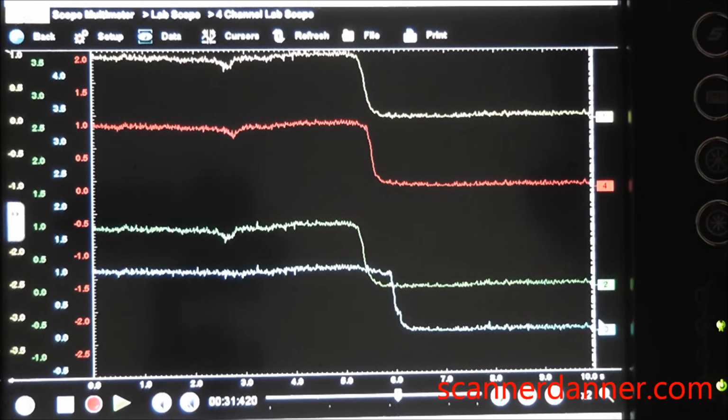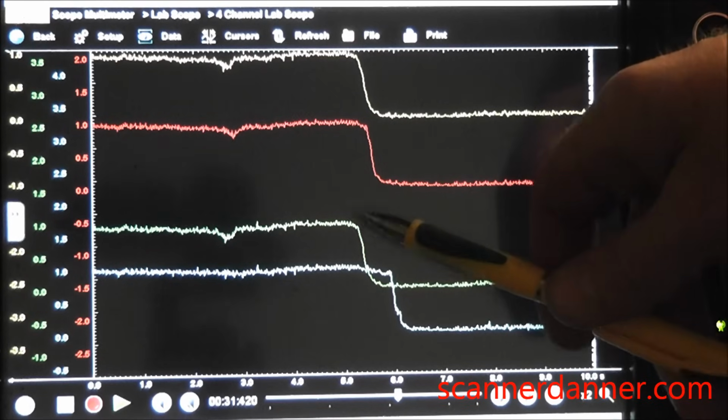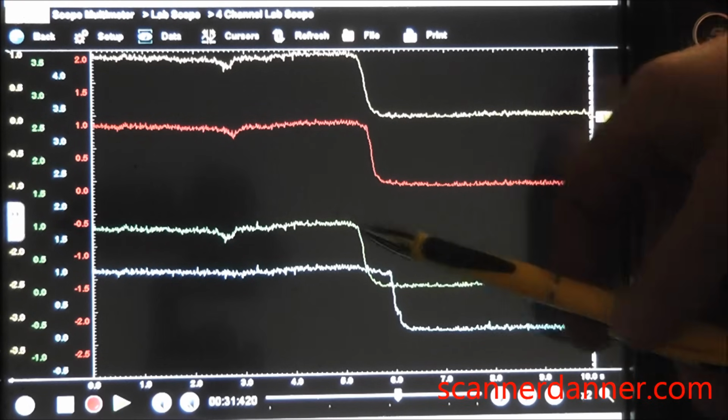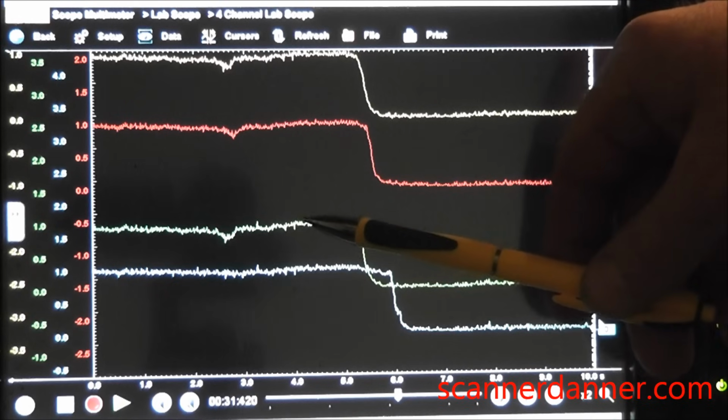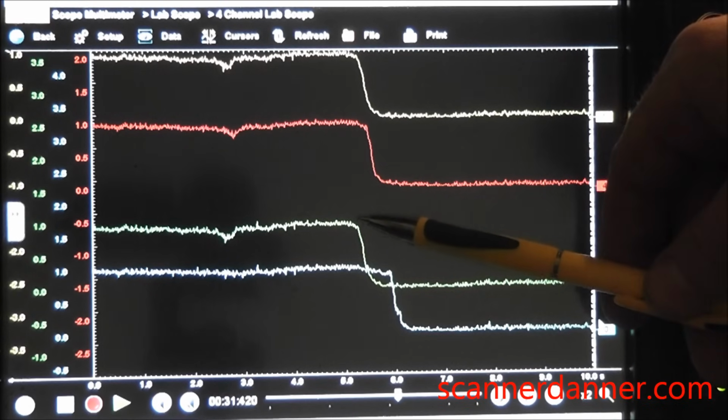That is where I turn the propane off. You can see that bank 1 is pretty much identical in time as far as oxygen storage goes, and bank 2 actually shows a delay. So again, upstream sensors here. I turn the fuel off.